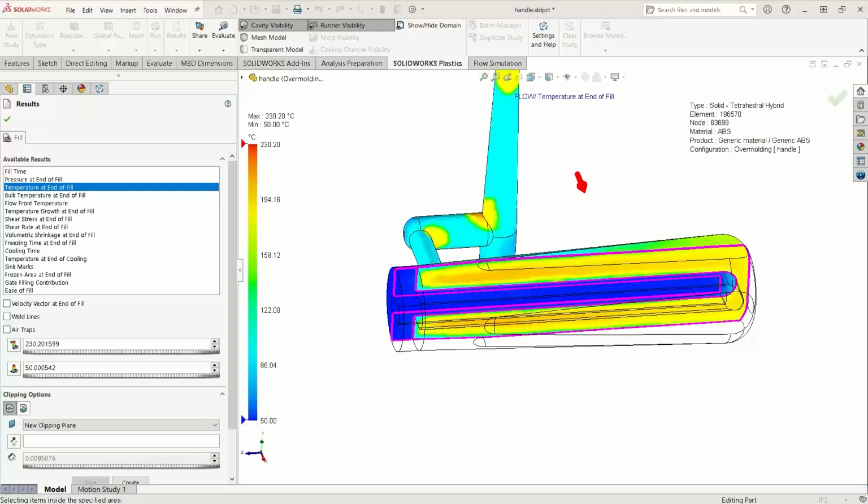Typically, the higher the concentration, definitely the better the mechanical performance, mechanical properties. But that said, there's a trade-off, right? I mean, the higher the concentration, it's going to be more challenging to process the material because the material tends to become more viscous, because of the presence of all the glass fibers, higher concentration of glass fibers.